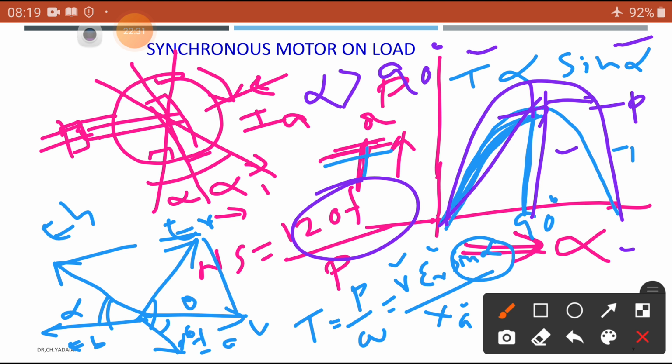The dampers consist of short circuited copper bars embedded in the faces of the field poles of the motor. Then the oscillatory motion of the rotor sets up eddy currents in the dampers due to Faraday's law of electromagnetic induction, and the induced eddy current flows in such a way as to suppress these oscillations as per Lenz's law.